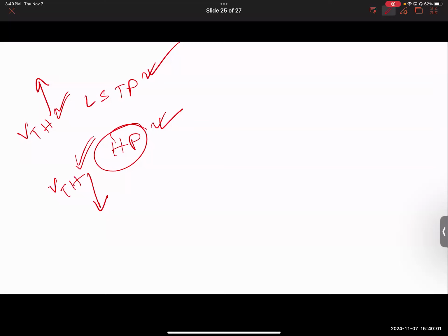Okay, so in circuit level, and I told you about levels of abstraction in this course: device, circuit, system. You might be a system designer or a circuit designer, agnostic to all these underlying boring phi ms and so on, right? But you need to change the threshold voltage in your circuit. If you have ever designed a circuit, this guy needs to have that threshold voltage, that guy needs to have that threshold voltage, especially in analog design. All sorts of threshold voltage required.